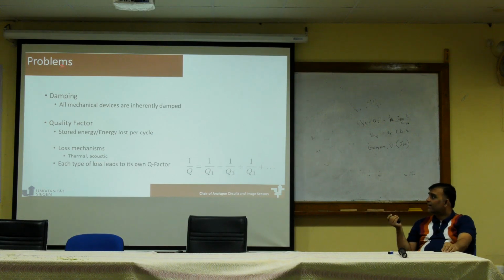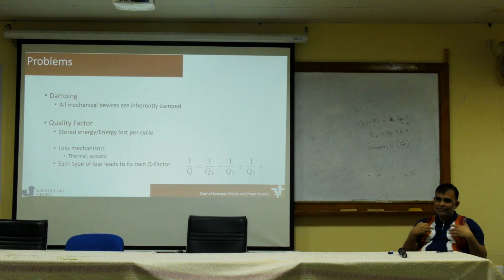And the other issue with MEMS is damping. All mechanical devices do not want to move. And when being moved, they want to stop their motion. Okay? We are not in free space, where once I start something, it will keep on moving. All devices here have n number of forces acting on them to stop them from moving, air being one of them.